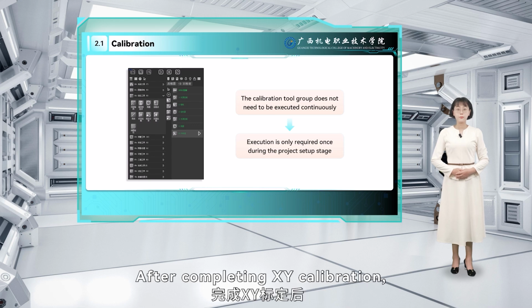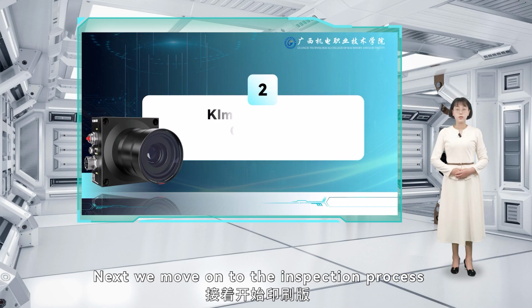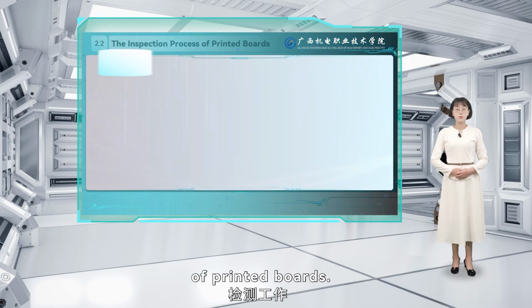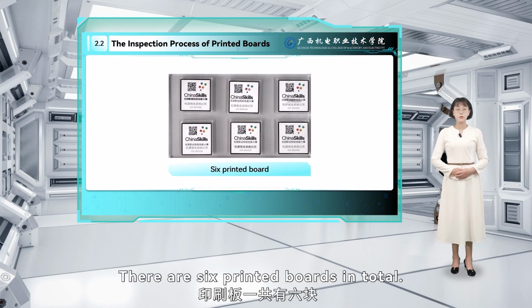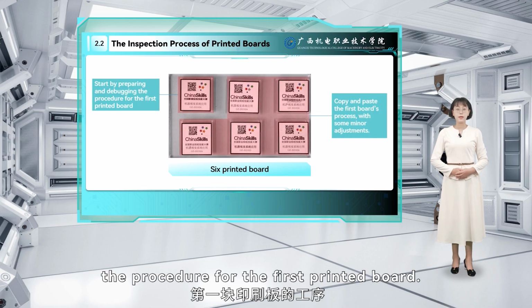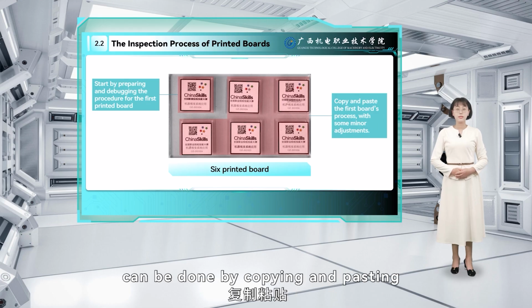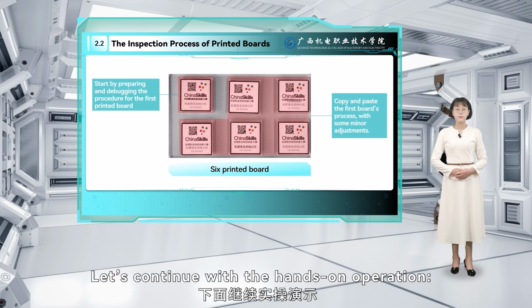After completing XY calibration, remove the calibration plate and replace it with a tray for placing mechanical parts. Next, we move on to the inspection process of printed boards. There are 6 printed boards in total. We'll start by preparing and debugging the procedure for the first printed board. The steps for the remaining boards can be done by copying and pasting the first board's process, with some minor adjustments. Let's continue with the hands-on operation.